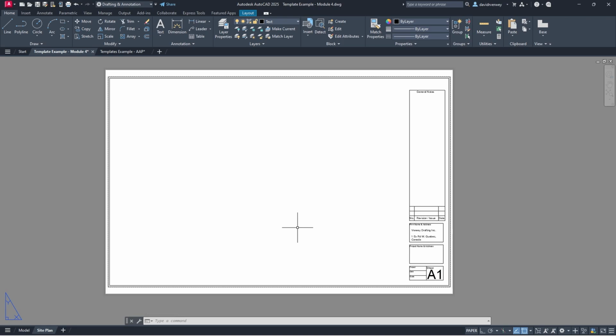Now, here's the thing. This title block is going to be good for this size sheet. Again, I've made tutorials about making a scalable one, but it's more efficient to just have a variety of title blocks for different size sheets. So I recommend that for whatever projects you're doing, for the sheets you use most, you create a title block for each of those, and that way you have your template set up. Because again, templates are going to save you a lot of time.